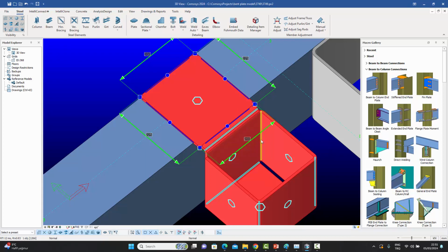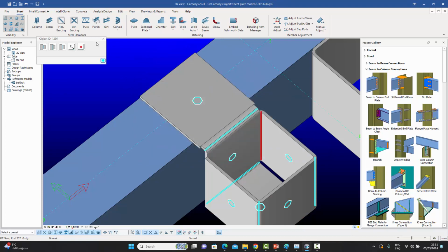And if you double click on these lines, then you have this new feature over here which allows you to bend according to the short edge. The two common edges might not be the same length, so you can connect the shorter edge or you can connect the longer edge, or you can make a tapered sort of connection.